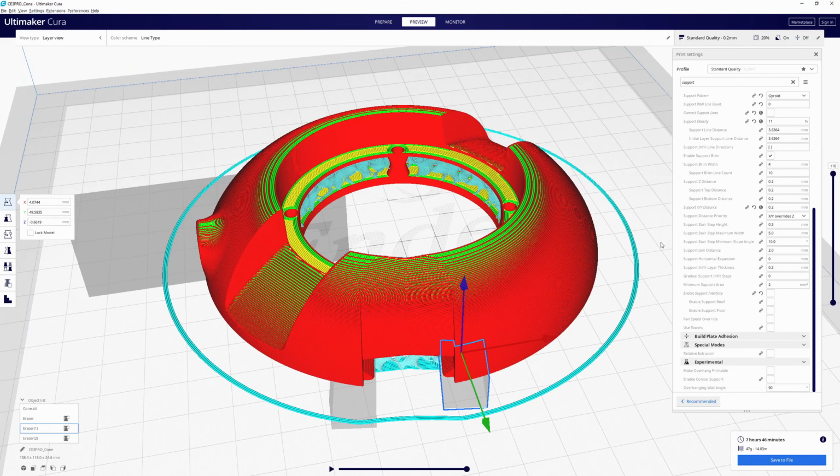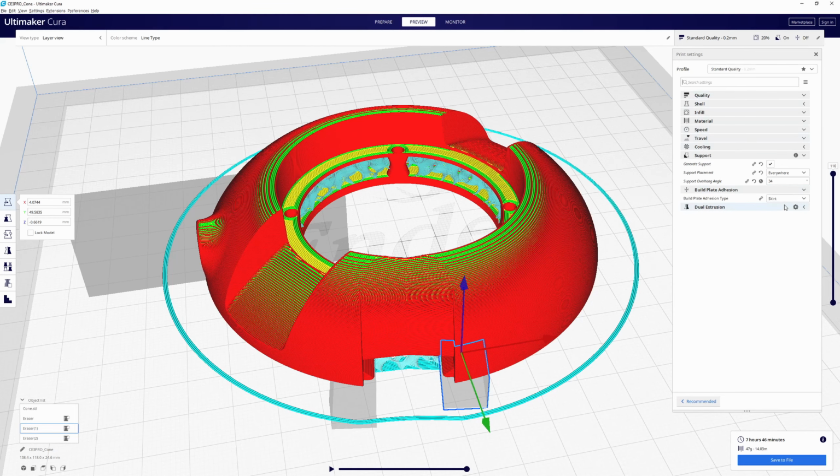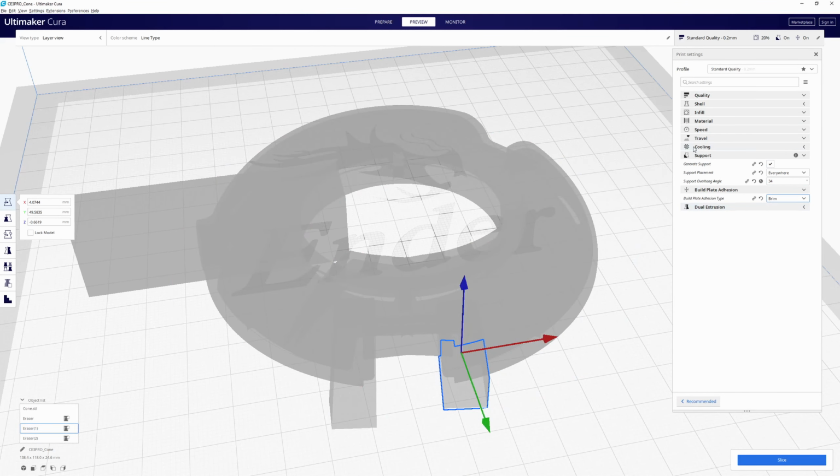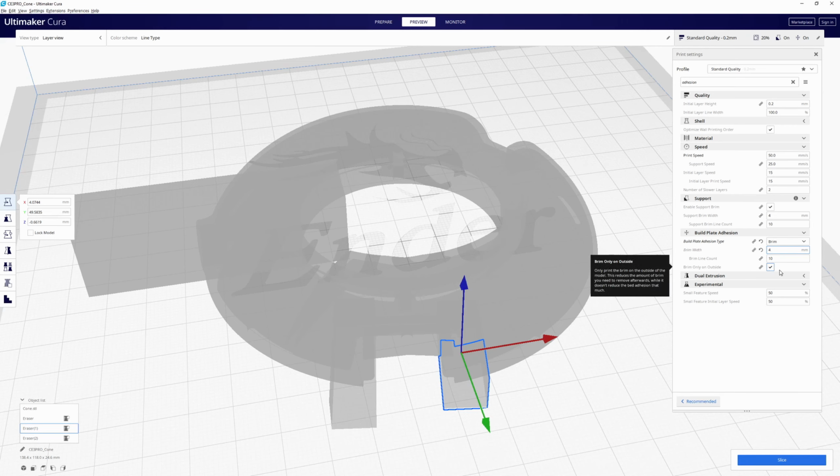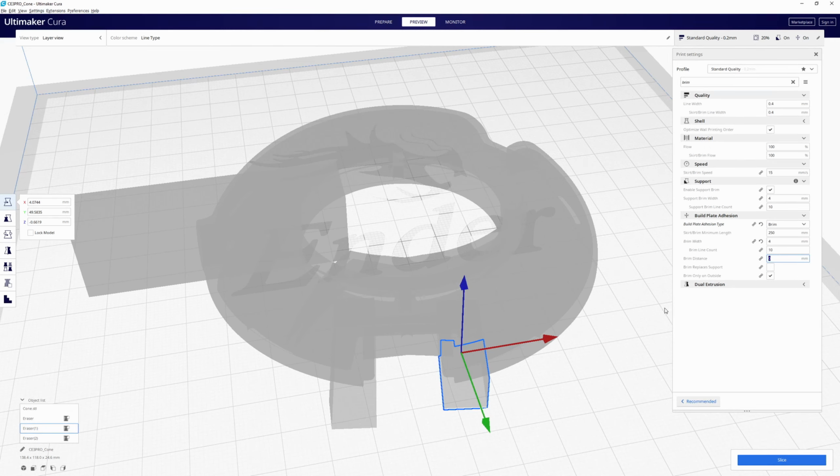Like we said before, if you need a brim here, I would change that for the build plate adhesion. We'll exit the support search, and we could click brim. And the default here is usually pretty wide, but if you want to open up those settings a little bit better without having to choose the correct basic, advanced, expert, then we can do just adhesion in the search. And you're going to see all the rest of the settings pop out here. So the brim width, usually I use a 4, and we're missing another one here. Let's search for just brim. Aha, brim distance. This one's a trick.